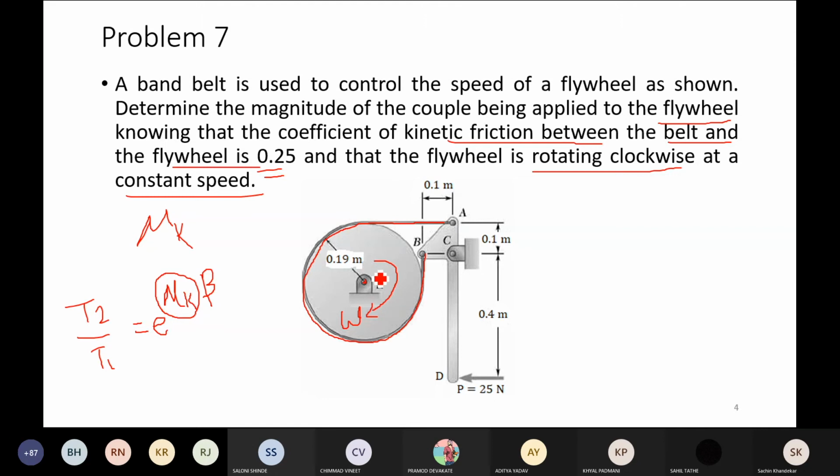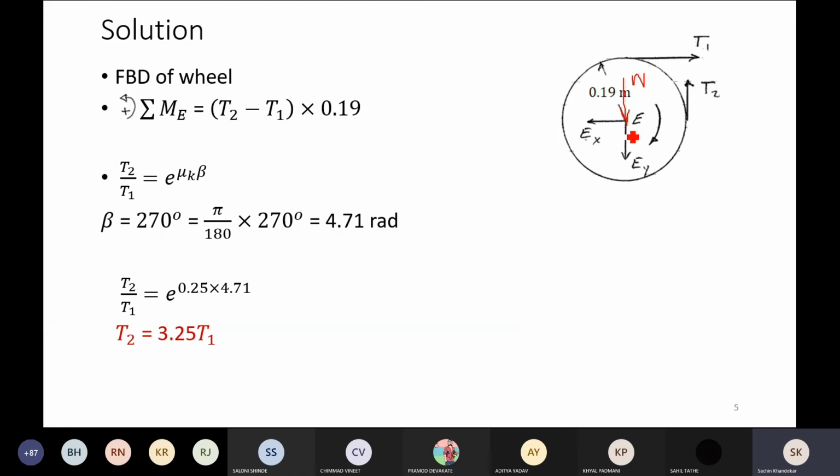Please note that this is a hinge, and that is why it is free to rotate, just like a door hinge. If I apply a force onto the door, it allows rotation. It opens or it closes after applying the force. But whether that hinge point moves from one location to another location, no. So that means hinge support doesn't translate, but it allows rotation. And as there is a hinge support, that is why we are showing the two reactions.